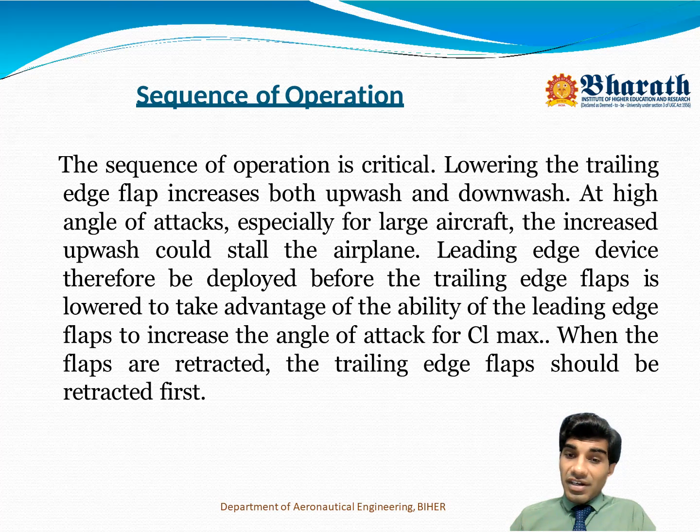When the flaps are retracted, the trailing edge flap should be retracted first. So if they want to close or retract them, first they are going to close the trailing edge flaps.